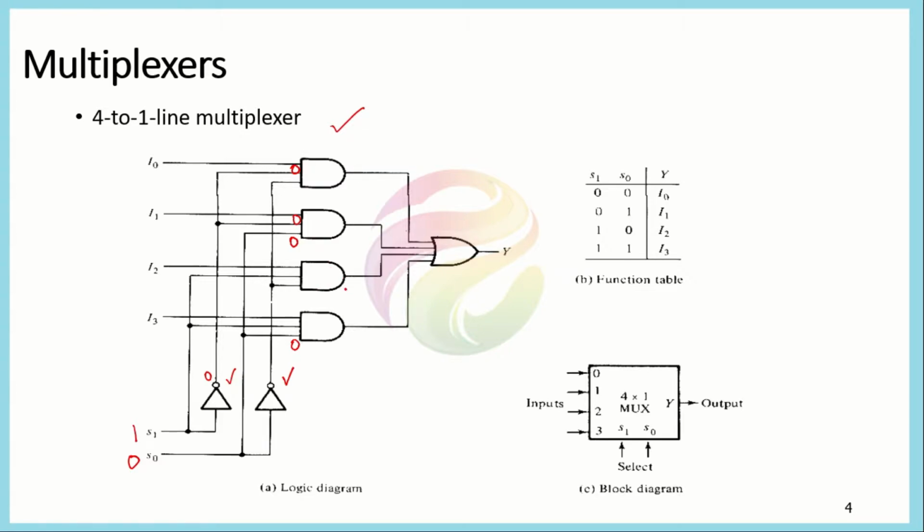So in this case we are only left with this AND gate in which both of the values are equal to 1, because from here you can see that S0 is connected here as 0. This would give us a 1 here, and this one is also connected here, and the other thing that is connected here is I2. So in this case the output of this AND gate would be equal to I2, and similarly when all other values are equal to 0 0 0, we would have only I2. So y is equal to I2.